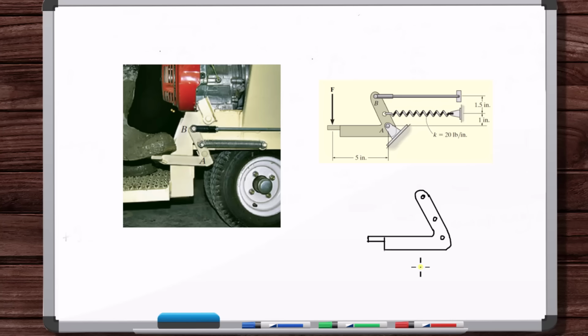there's only one other type of force in the universe, a surface force, contact force. What does that mean? That means that any force that's acting on this link is going to come from contact with something. If there's no contact, there's no force. There has to be contact. I'm going to say this again because it's really important and really helpful. Once you've accounted for the body forces, then all other forces on your free body diagram, on your component, are going to come from contact with something, right? If you come back to the environment it was in, there has to be contact with something for there to be a force. There has to be contact.